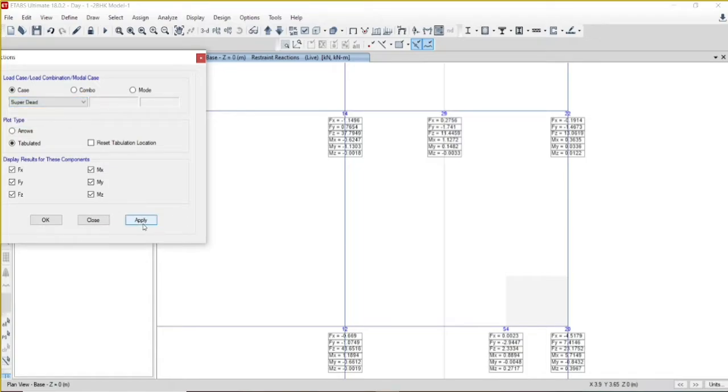So to design, here itself in analysis you can look into the reaction forces and you can make the design adjustment. And due to super dead load, you might see that 170 kilonewton of load which is the maximum, and at X and Y you have the respective load here. Now let us check the load combination. This will be very much higher than the previous.